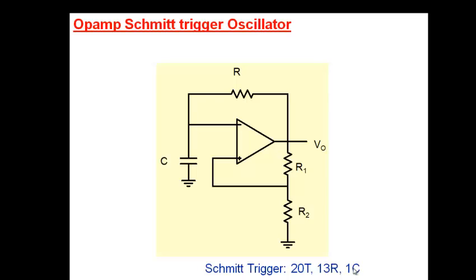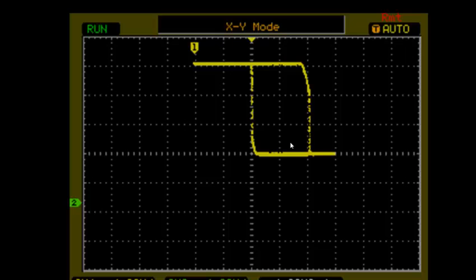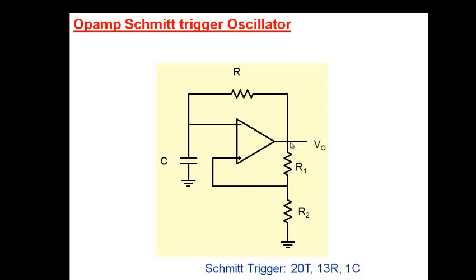So what I'm saying is, yes, you can make the design modular, but the modularity often comes at a price. In order to ensure that the two do not interfere with each other at all when you connect them up, you have to take certain steps. For example, you'll have to build very high input impedance here and very low output impedance here, and that makes your design complicated. On the other hand, our design is very efficient.